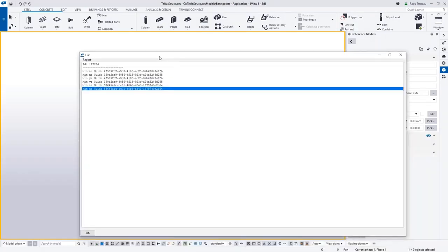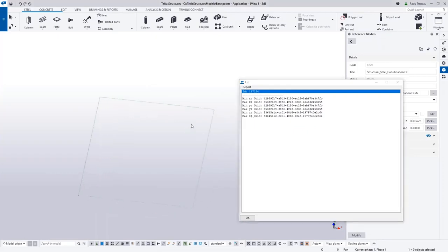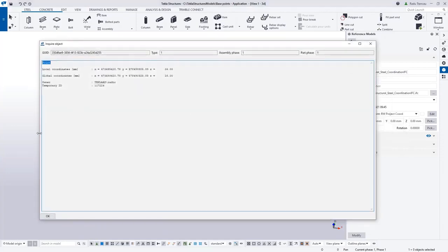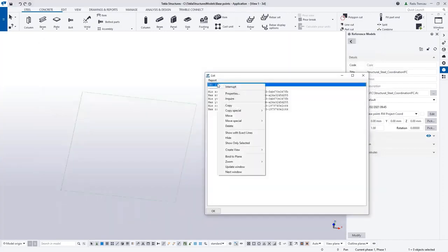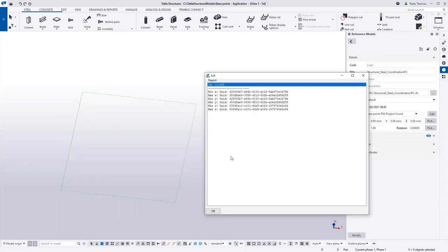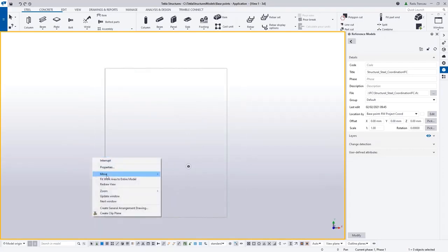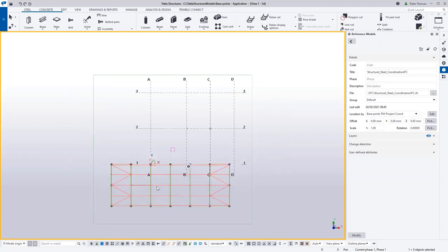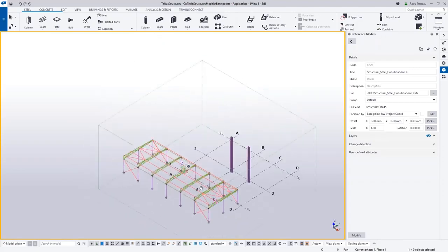Objects. Okay, so you should get a window with a point, right? That is the point that I've just missed in that corner, and I wish it to be deleted. You can just inquire the object and you will find what it is in here. So quick way, go here, right click, delete, and that should clear the problem for the next fit work area to entire model. Okay, that's a very simple solution to a very common problem that we've seen.